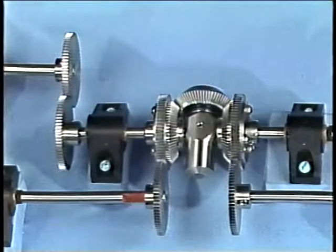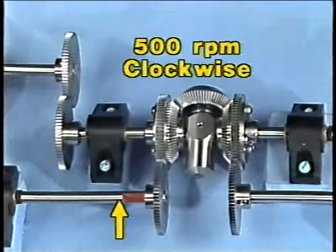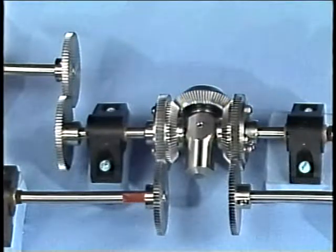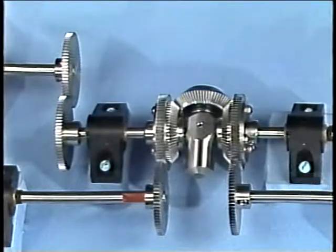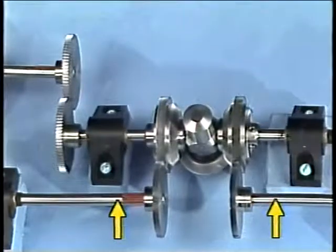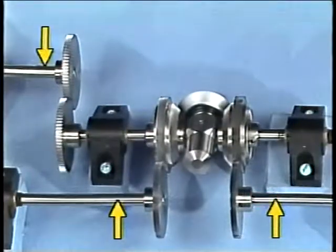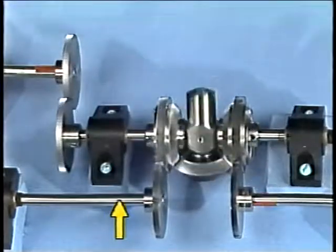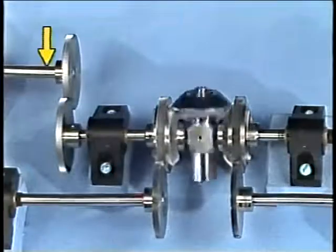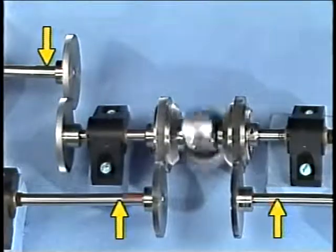To get a better picture of how the differential compares inputs, let's change the speed and direction of rotation of these 2 shafts. We'll rotate this shaft at 500 RPM in a clockwise direction, and this shaft at 500 RPM in a counterclockwise direction. In other words, we'll provide inputs that are exactly opposite. Since the inputs are exactly opposite, they cancel each other out, and the differential provides no output. If we slow down this shaft, the differential now sees a difference in the input speeds, and the output shaft rotates. The output speed is proportional to the difference between the input speeds.